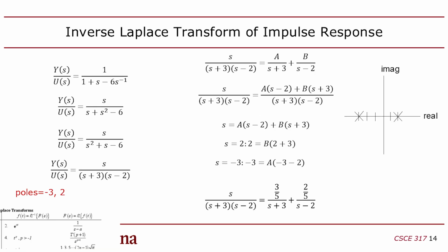So generally, if you have a plot where the real part is the x-axis, right, and the imaginary part is the y-axis, you want all of the poles, which are usually marked as x's on here, to be on the left-hand side. If they're all on the left-hand side, meaning the real part of each pole is negative, then you're good. It's stable. Make sense?